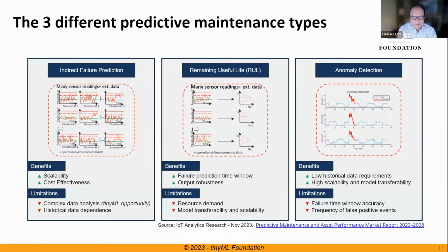For me to get the direct prediction of a failure, I'd have to disassemble that motor and inspect the bearing and find that I have grit or a fault or something that's gone wrong in that bearing. But instead, I don't need to do that. I can typically just put a vibration sensor on there and pick up the frequency that corresponds with the rotating frequency of that device, and it becomes a proxy that's highly correlated with the actual fault that I'm looking for.